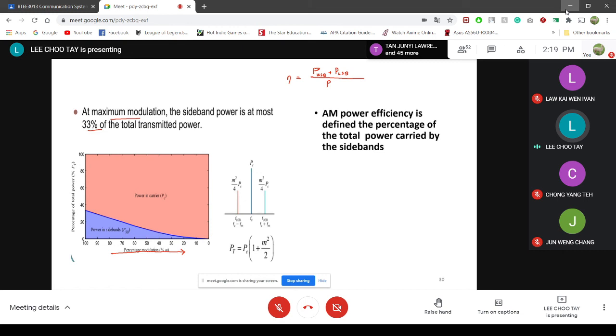And per decade, meaning 10 times my cutoff frequency, I'm going to have minus 20 dB attenuation, which equals 1 over 100. So at 10 times the cutoff frequency, which is 500 kilohertz, the frequency component at that frequency will be reduced by 100 times.